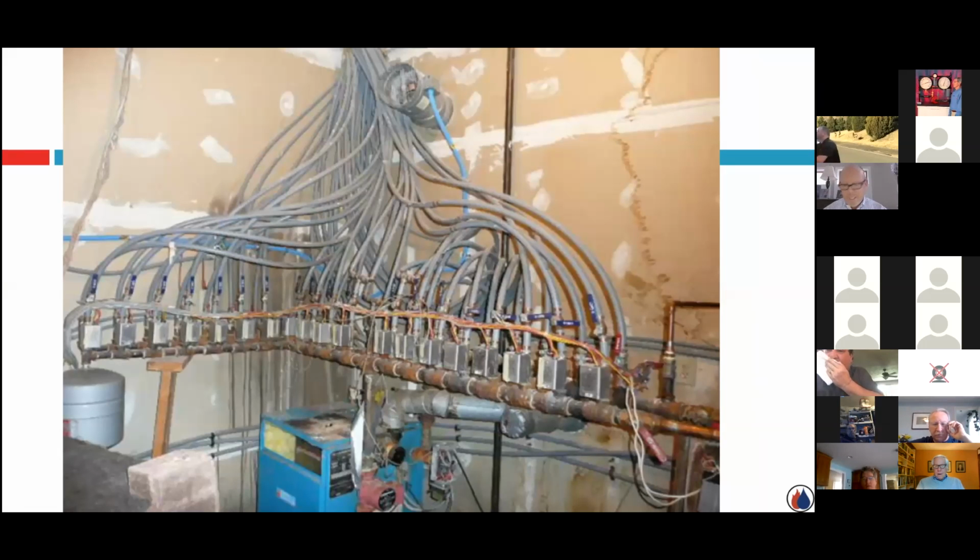You got this little boiler here. You got this little Grundfos pump feeding this manifold of like 15 or 18 zone valves, looks like maybe Honeywell zone valves, feeding PEX tubing. And this certainly screams of a picture of a do-it-yourselfer. It's amazing. And again, how they get heat upstairs, it's just amazing. Got a little expansion tank hanging off to the side here. I don't see any air separation, so I don't know how they're handling the air that might be developed as you heat the water in the boiler plant.